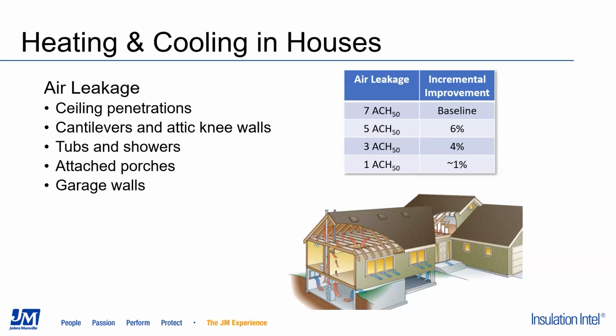Our homes have got a ton of holes in the ceilings, whether that's light fixtures or even holes that we might not always see because they're buried in the walls, things like plumbing vent stacks and the flue for your water heater or your furnace. All of these things require holes that go up to the ceiling and roof. Those holes all need to be sealed off.